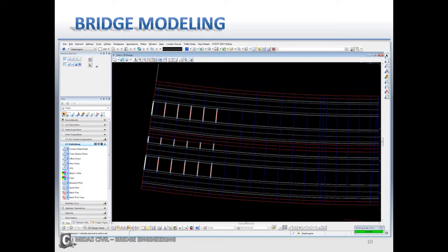And what I'm going to do is bring these nodes into MIDAS. I want to import the nodes versus importing the actual elements because the tub girder is a little more complicated, in particular because of the cross frames being in the interior and exterior. If it was an I girder, it would be a little bit easier to import the elements as well, but because it's a tub girder, it's a little more difficult. Now that being said, you can do it. I just prefer to import the nodes.